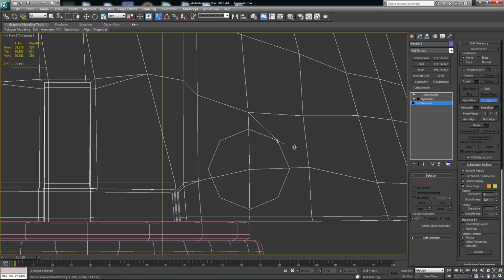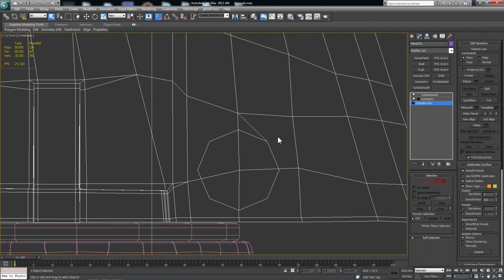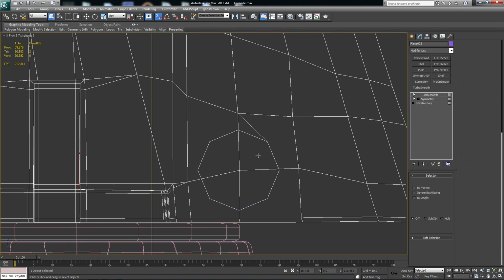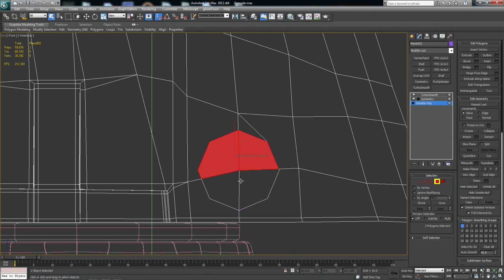This will continue to update throughout your cut, so just continue around the shape. Notice that the depth of our guide doesn't matter as long as we are in a flat view like front, side, or top. Double right click to end your cut and deactivate the cut tool. Cut can be really frustrating if you haven't used it much, so the double right click is a good trick to remember. Otherwise, you'll just keep cutting up the mesh until you punch your monitor and explode yourself in your room. Okay, now switch to face mode and delete the inside faces.